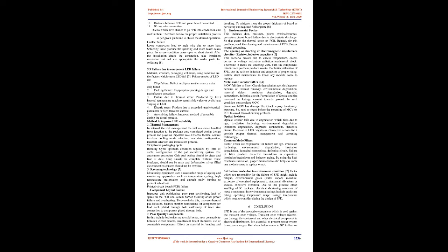10. Shorting or opening of any protective circuitry including a fuse, thermal protective device, or circuit breaker. Caused by a latching problem of the circuit breaker, failure to operate the protective device, or selection of a fuse and protective device of improper rating. Hence, an increase in internal overcurrent has a chance of burning and damaging internal components of the SPD. Corrective action on it is to check the latching of the C.B and tripping setting.